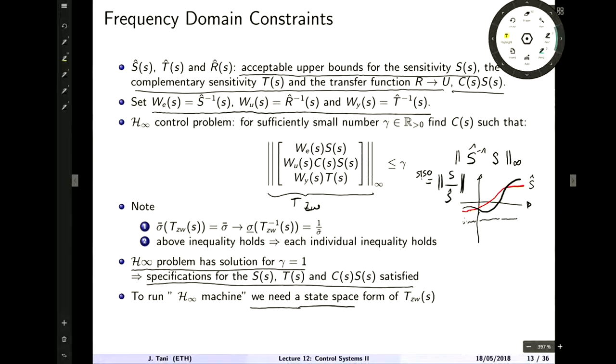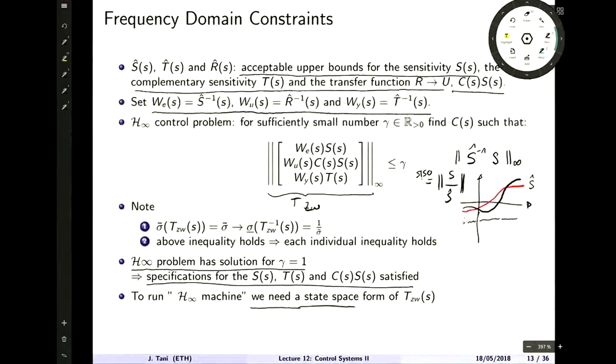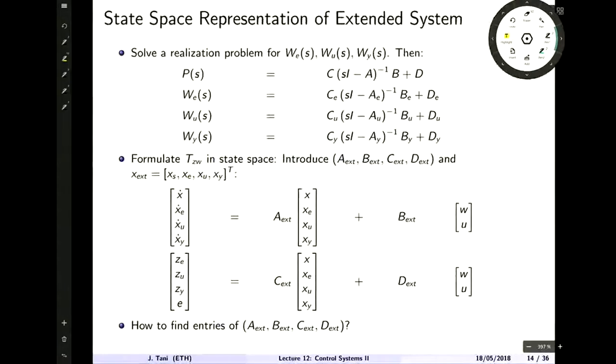So MATLAB and other software will ask you for a state space representation of the extended system, which is why, and I want to show you these steps, we need to make an effort to move our design, which is very intuitive and very understandable in frequency space, to state space. And this is where part of the mess starts. First of all, we have these frequency space representations, so we first need to put all of them to state space, right?